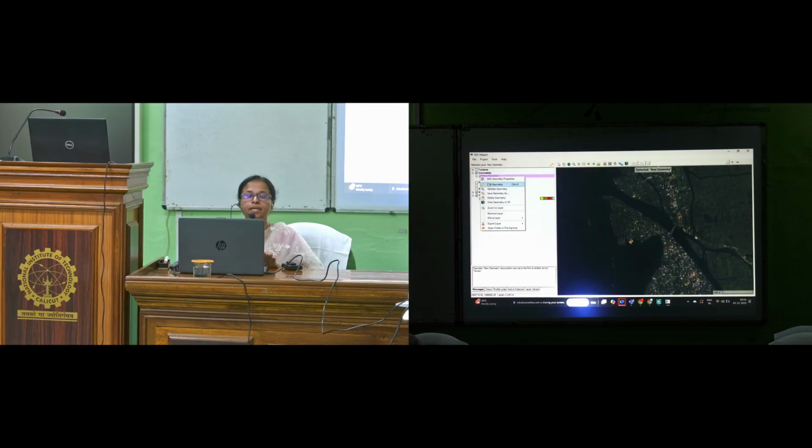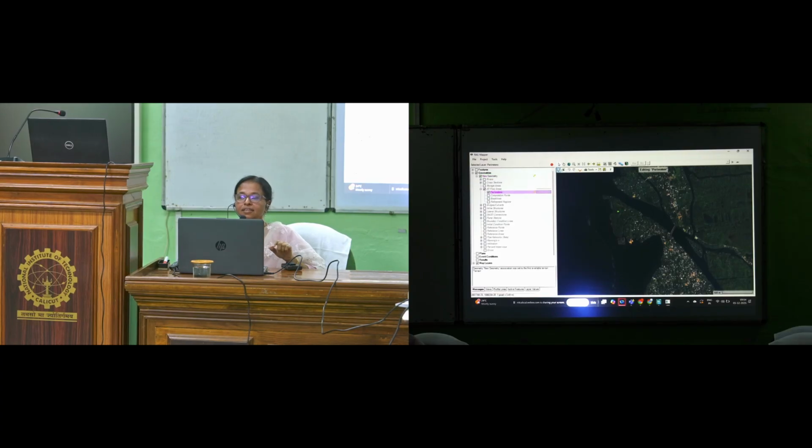Then edit geometry. Here you can add 2D flow. I am going to develop the 2D model. So you have to select 2D flow area, then perimeter. Select that. Then you can see a green color here. So you can draw the area. Then double click.